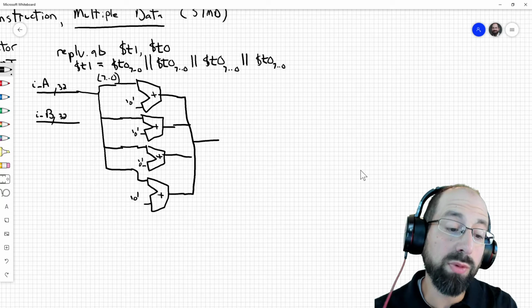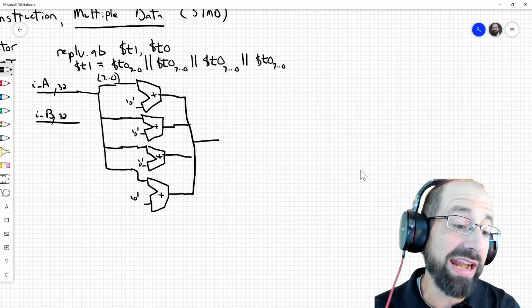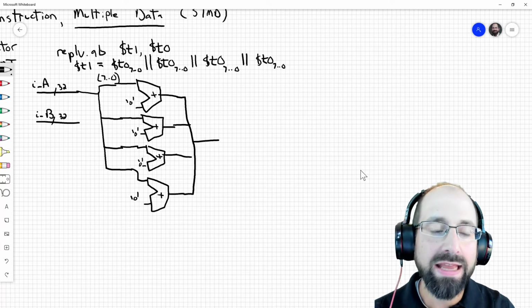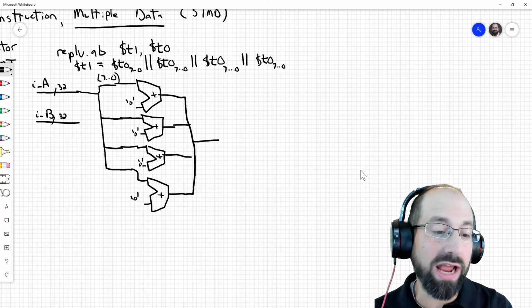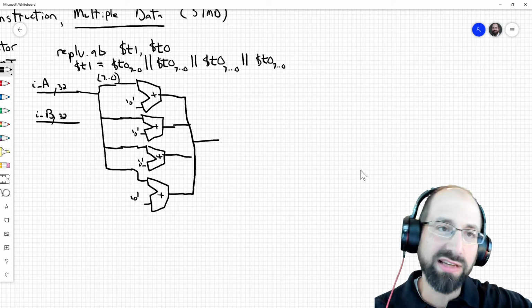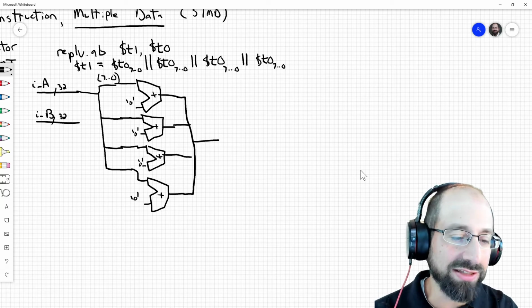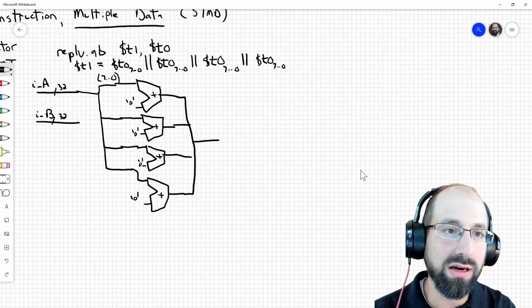Yeah, and in our implementation, at least so far, all of our adders are basically 1-bit adders, right? With our ripple carry design. So it doesn't really matter since we're adding 0. You can think of it as a single 32-bit adder or individual bit adders. I just drew it as 8-bit adders here because we can group the hierarchy logically to draw it relatively simply there. That'd be one way to do it.